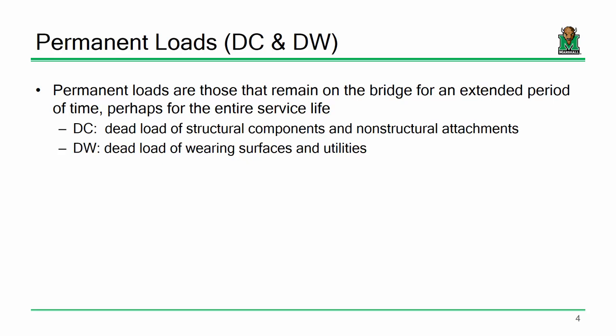So let's start off with the easy part. Let's start off with the permanent loads, the loads that always sit still. In other words, the dead loads, okay? Now, we really have two dead load force effects that we need to consider for highway bridges, specifically the bridges and components that we're dealing with, and those are DC loads and DW loads. If we were looking at substructures, we might have EH loads, earth horizontal pressures, and things like that. But for what we're doing, DC and DW.